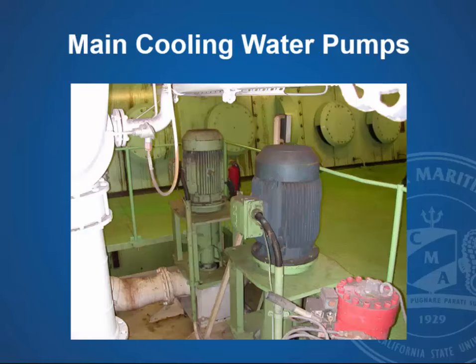In the Kongsberg simulator, in many instances, both on the freshwater side and on the saltwater side, you have three pumps. You basically have two main saltwater pumps that are redundant, and you would never typically run both of those pumps. Again, if you were troubleshooting and you thought that one of these pumps had a low flow rate, what you would do is you would put the redundant unit on, or the standby unit, and shut the one that you think has a low flow rate down and see if that solves the problem.